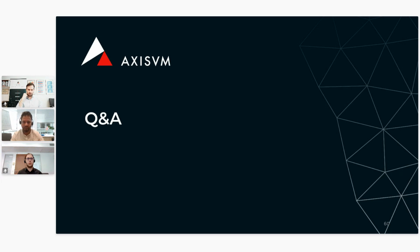You don't have to do that. Basically, you can mix different kinds of actions: adding elements, removing elements, modifying elements inside one construction stage. But when it comes to the analysis part, the software will need to know which happens first and which happens later.